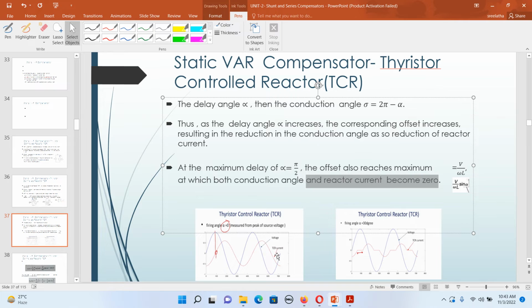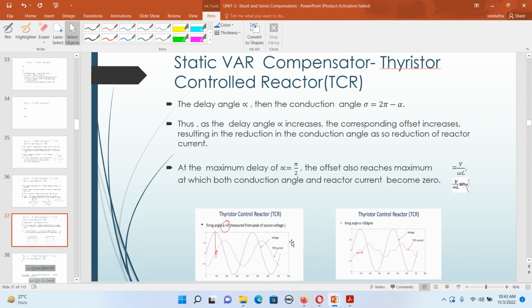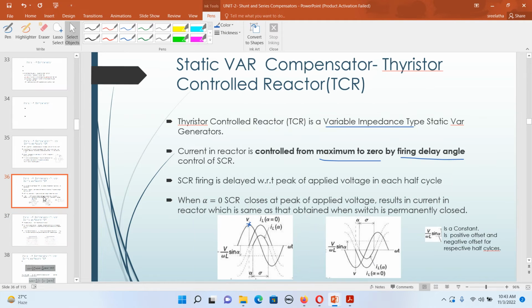However, the thyristor TCR current is... So this is the current. This is the TCR current that we are talking about. This is the voltage. Okay, when alpha is 30 degrees, you see, we did not turn on till this point. So our TCR current reduced, and same thing. This is a MATLAB program, I think. You can also write the same MATLAB program. Just use these equations.